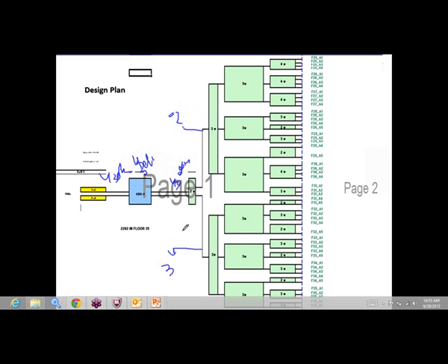Okay, so it is 3 dB, it will be 40 dB, correct. Okay, so this is 40, this is 40. So then I'm splitting this again. I want to calculate the power for this antenna. So all the antennas are go. So this is a three-way splitting again. So this is 40 watts because it's split. We did the splitting. So this was 40 watts.